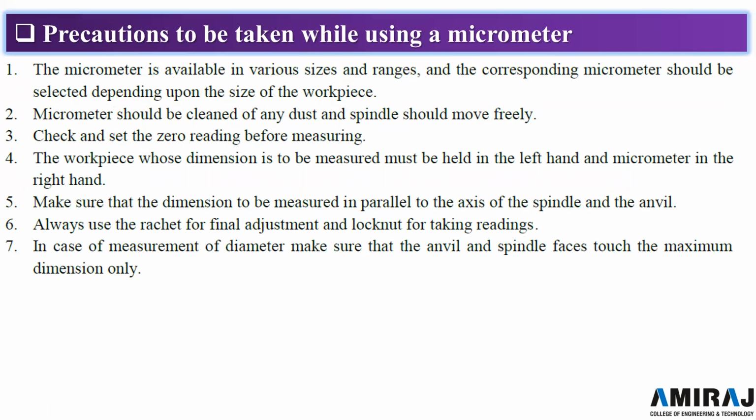Next, these are the various precautions to be taken while using a micrometer. The micrometer is available in various sizes and ranges, and the corresponding micrometer should be selected depending upon the size of the workpiece. It depends on how large the diameter of the workpiece is or the length we are supposed to measure.